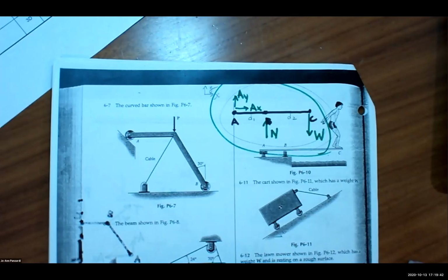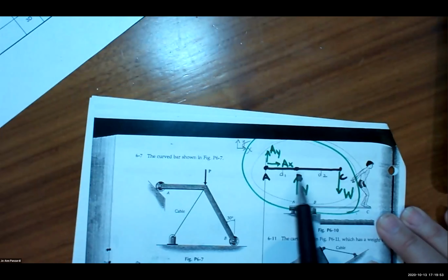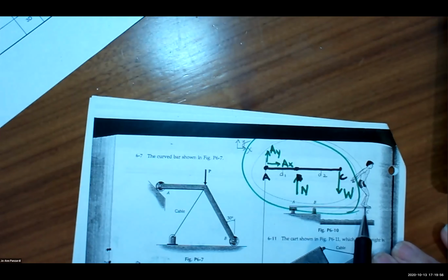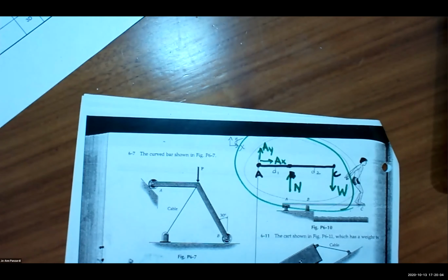I thought we were only taking the weight when there's a little G. Yeah, but they're talking about the weight of the body. So there's a little G here because they want you to include the weight of the beam. Here, the diving board is negligible, so you don't use the weight of that, but you still have to account for the external load of the weight of the person on it. Good question. And the reason why in statics many times we ignore the weight is because the weight is so light in comparison to other things.